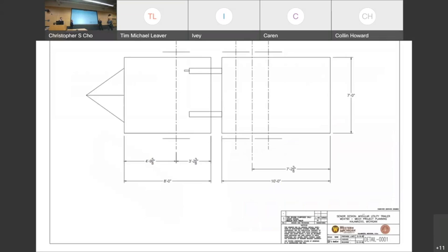So one thing that we've done early on was doing some field research within different trailer companies. We had gone down to a trailer manufacturer in Vicksburg to take a look at some of their different configurations. We got some measurements off of those configurations, which helped us determine where we were going to place the center lines of our axles. This was important because we wanted to make sure our weight distribution would be safe, even with a fully loaded vehicle hauling trailer.